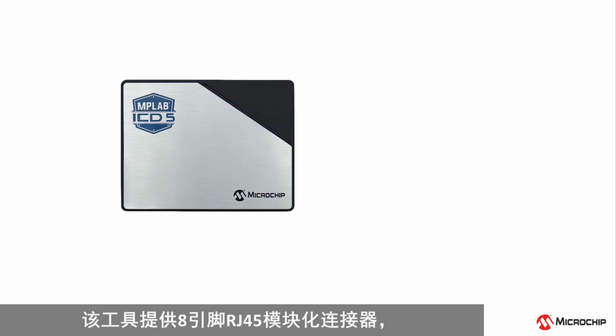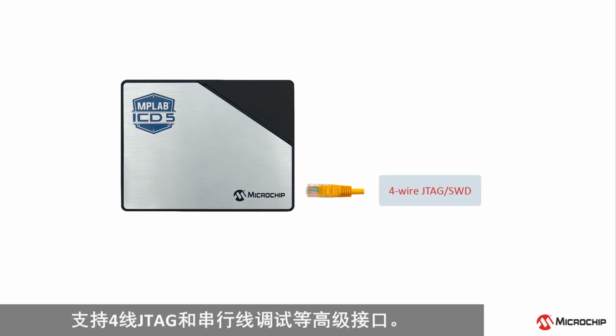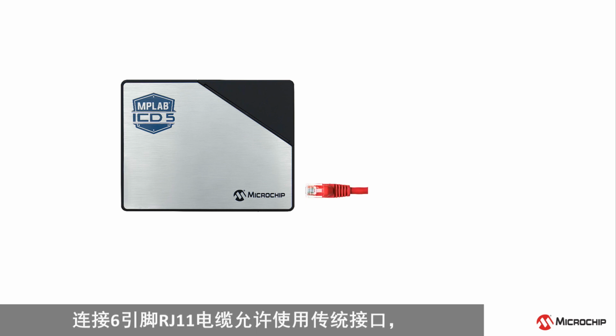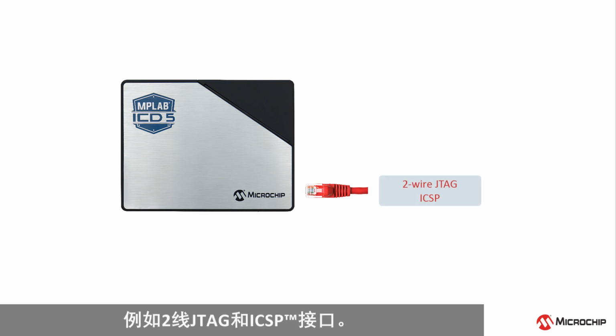The tool provides an 8-pin RJ45 modular connector, supporting advanced interfaces such as 4-wire JTAG and serial wire debug. Connecting a 6-pin RJ11 cable allows legacy interfaces such as 2-wire JTAG and ICSP to be used.